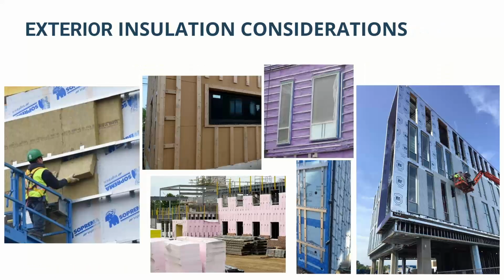There are a lot of different types of exterior insulation, and there are some important design considerations that need to be accounted for, right? Number one, it's in a wet space, so it has to be able to get wet. So you're limited there to either mineral fiber or foam board insulation, whether that's EPS or XPS or polyiso, or spray foam, so medium density spray foam, closed cell foam. That's another option there. But then you also need to think about vapor permeability of the exterior insulation.